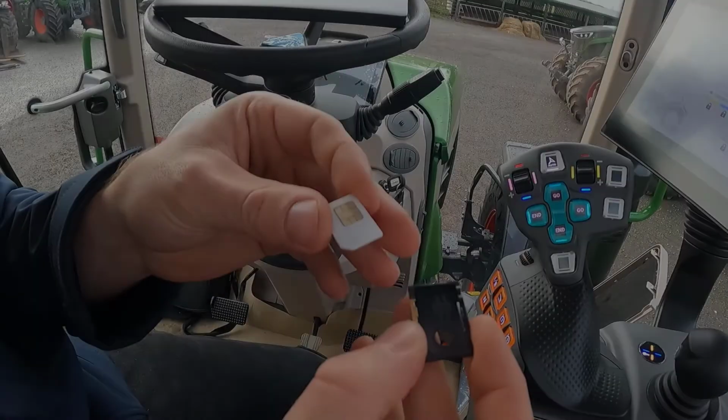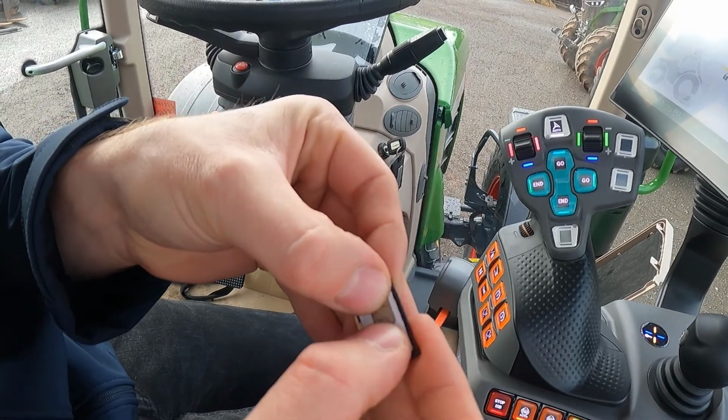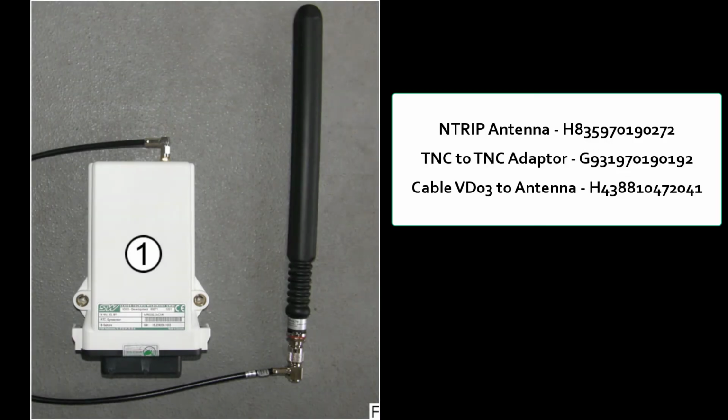The SIM card is installed into the tray, taking care to make sure it sits flat and true. Then place the tray back into the unit. Note that to utilise RTK NTRIP on either a Novatel or Trimble receiver, the receiver itself needs to be unlocked to centimetre level. Also pay attention to the fact that a small antenna cable and aerial are also required when using RTK.